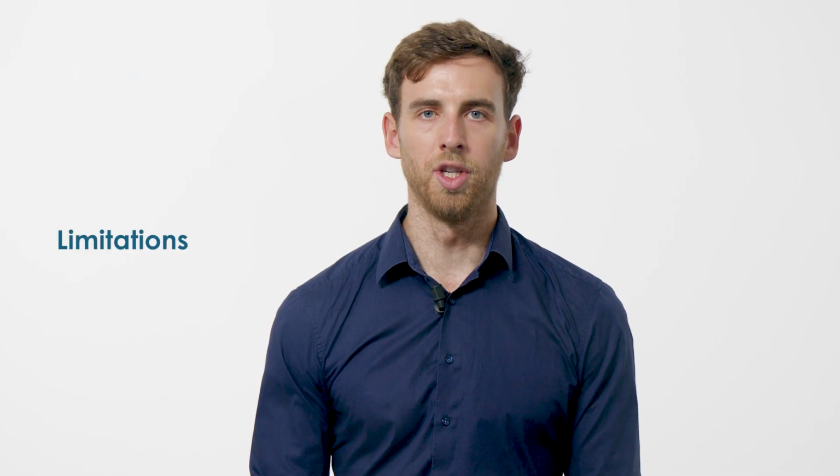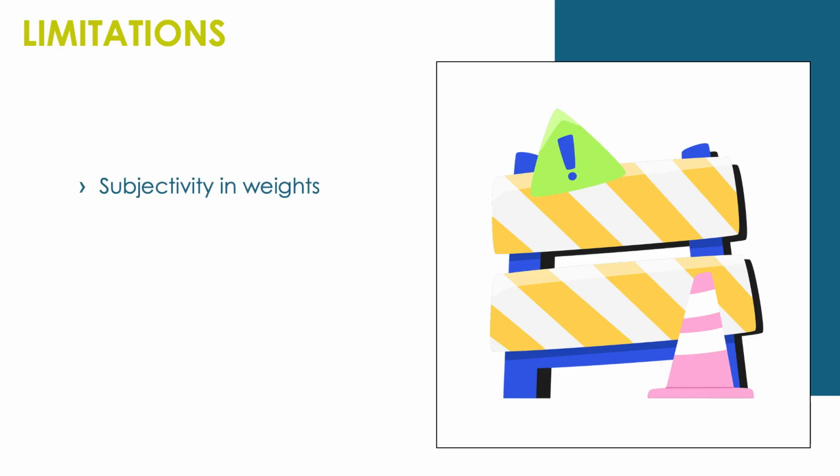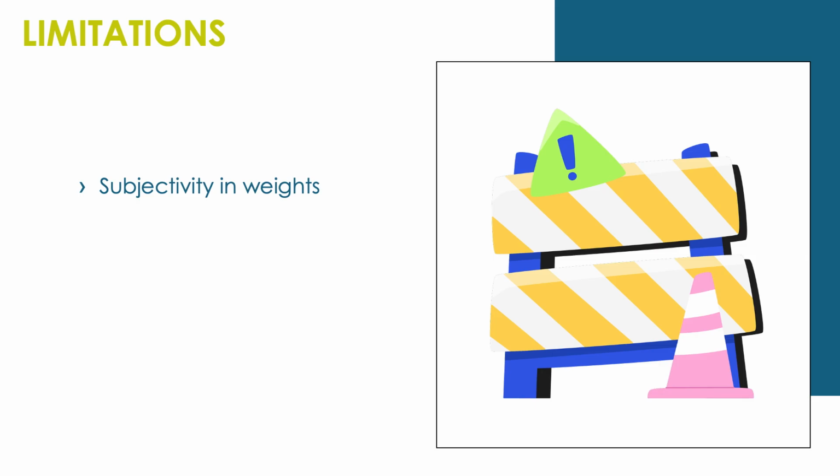We also need to talk about limitations and assumptions of MCA. As powerful as MCA is, it also has limitations. You need to be aware of these to avoid overconfidence in your maps. Subjectivity in weights, unless grounded in expert inputs or formal methods, is one of the most important. Weights can introduce bias. Also, MCA intrinsically simplifies real-world problems, assuming independence between criteria. But in reality, for example, terrain and infrastructure may correlate.